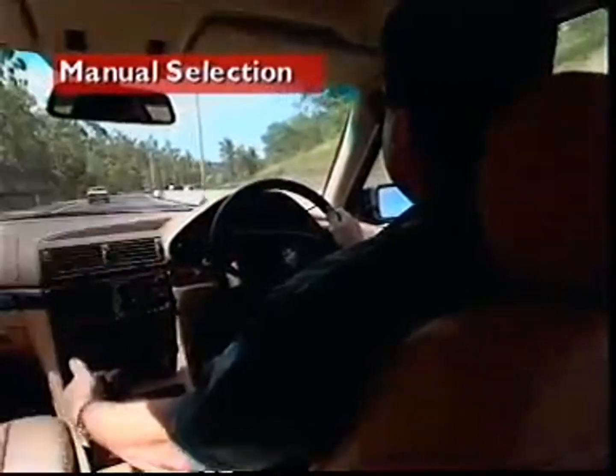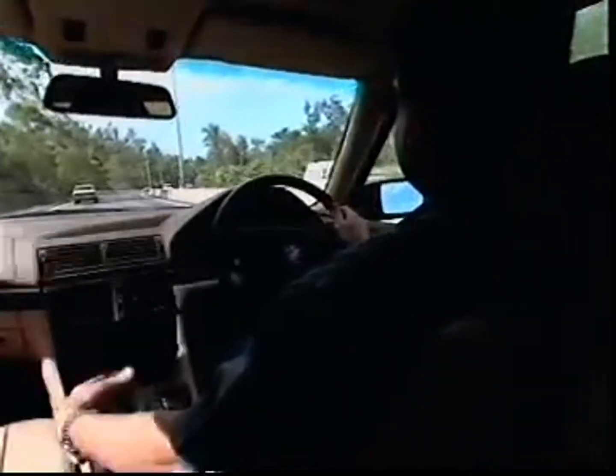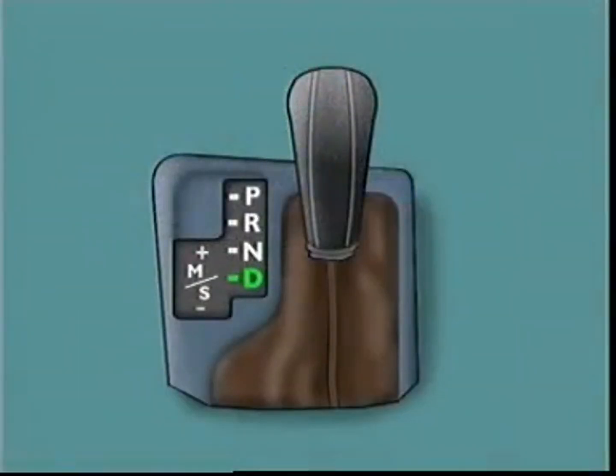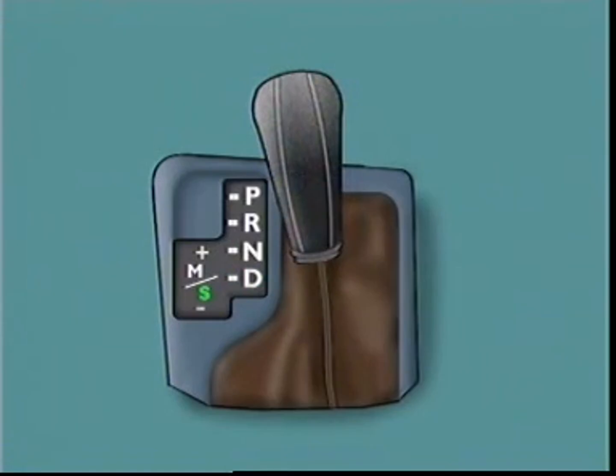Despite the benefits of adaptive control, a particular ratio can still be selected manually. In Steptronic applications, the manual program is available by moving the selector lever to the left of the D position. Automatic changes continue in a sport program until the lever is operated in a one-touch movement towards the manual mode. Forward movement changes the transmission to a higher gear. Backward movement, to a lower gear.